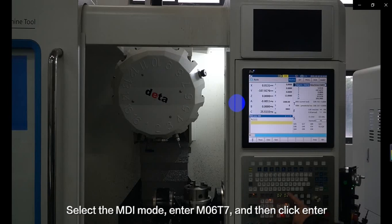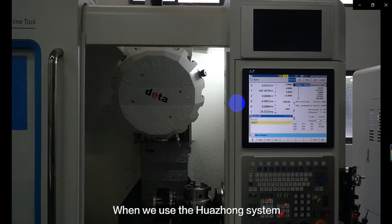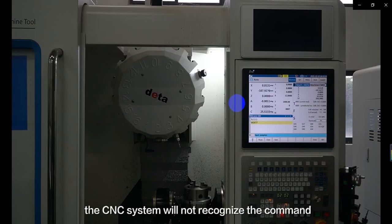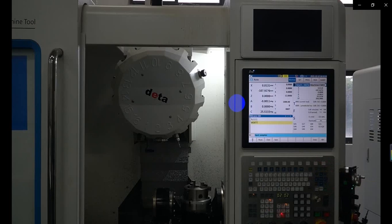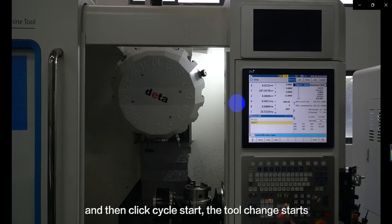Select the MDI mode. Enter M06T7 and then click Enter. When we use the Huazhong system, if you do not click Enter after inputting the command in the MDI mode, the CNC system will not recognize the command. After inputting the command, click Enter, and then click Cycle Start. Then the tool change starts.